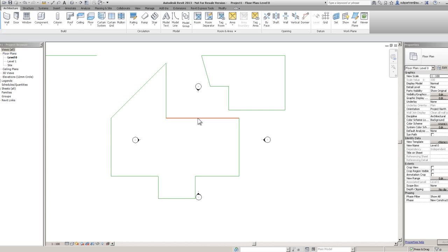Can you see how it's flashing? It's basically choosing very quickly between them, just rotating between different things that we can select. So literally all you do is just touch the tab button. When you touch your tab button, can you see how every single line within that chain soft selects? Can you remember, if we go back a couple of minutes, what I said was anything that is soft selected, if you just left click, it will select that. Well, this is why it does it.